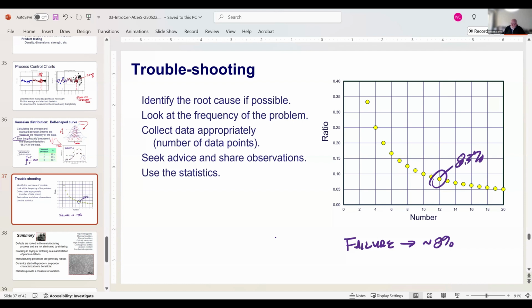So the thing is that they were casting in that suspension, they were casting these plates, and as they were casting in the time required, it sounds silly, 11 were fine, the last one there had been sedimentation, and that piece always cracked. And by stopping halfway through and mixing that slurry in their slip casting, that problem went away.